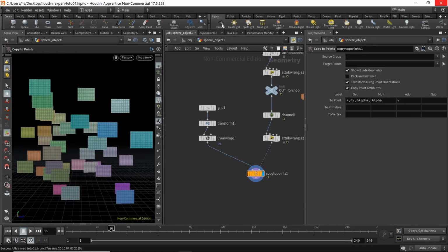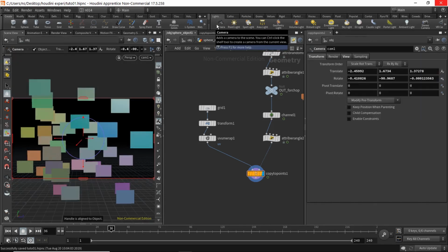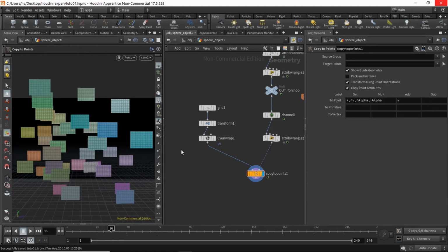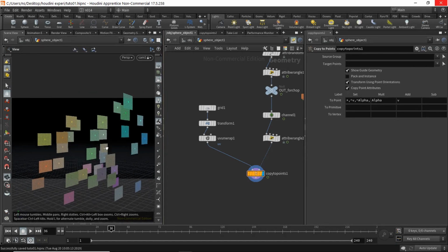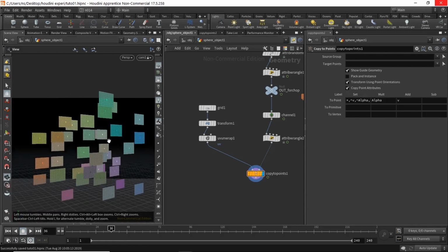and now we have to create a camera as well. So just keep pressing Ctrl key, and then as we click here, it has created a camera from this view. Okay, so switch over to camera viewport and just press this lock button here as well. As we move the camera, we would like these planes to be always facing the camera. We want them to work as sprites.